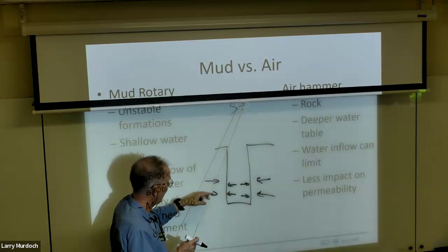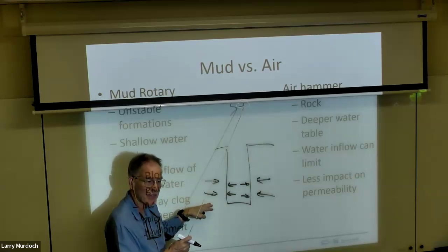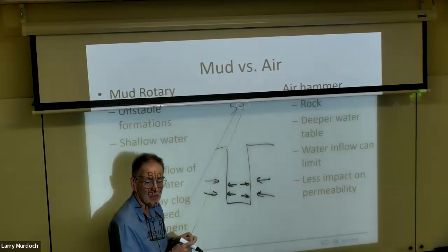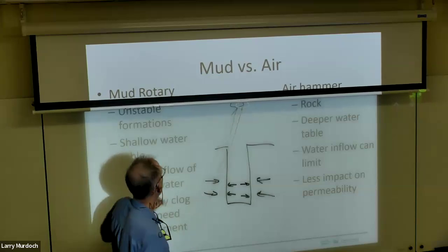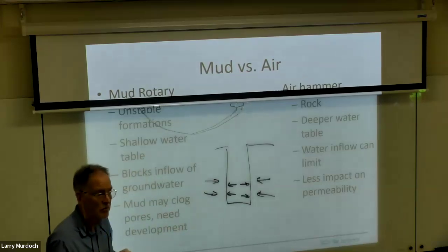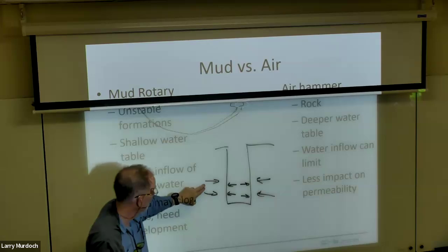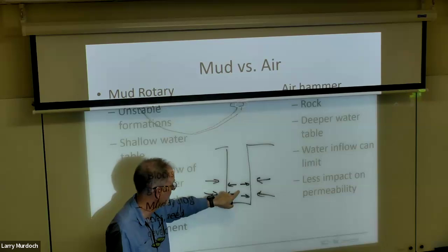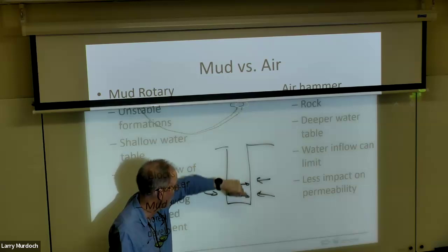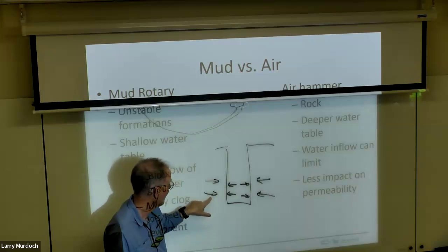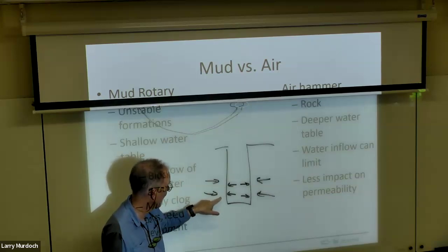But this stress in the rock will be at least from the lithostatic pressure, lithostatic stress. So rocks are denser, the unit weight of a rock is greater than water by 2 to 3 times. So this is going to be greater than that if it's water. But if you add mud to the mix here, that increases the density and helps stabilize the hole because it increases the stress that's countering this stress that tends to make the hole collapse.